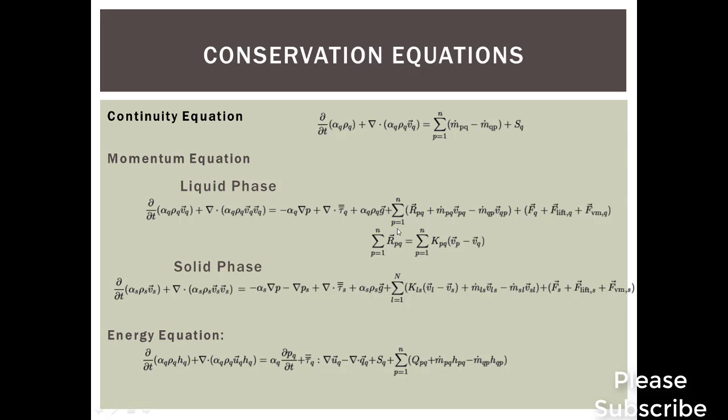Rpq, as I stated, is the momentum transfer that occurs due to this transfer coefficient, or the momentum exchange between solid and liquid. This is the transfer coefficient Kpq. Vp minus Vq is the change in velocity between the two phases.